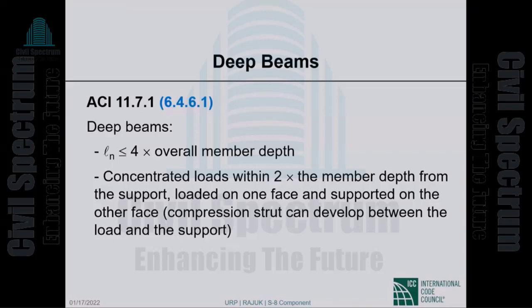The concrete contribution has multiple parts: the shear in the compression concrete, the dowel shear, the aggregate interlock shear, and all of that we kind of lump together in typical applications. Anyway, then for design purposes, minimum reinforcement, the maximum spacing. So we have covered everything that will enable us to solve real life problems, and we will do one or two of them.